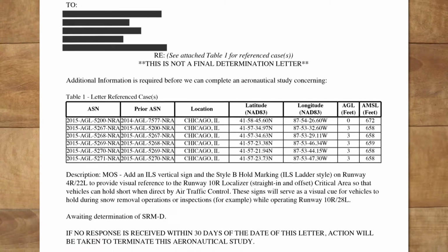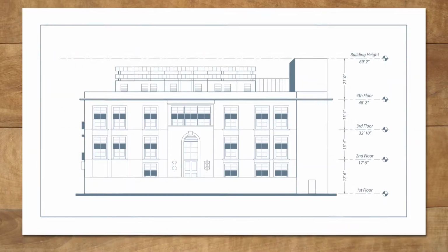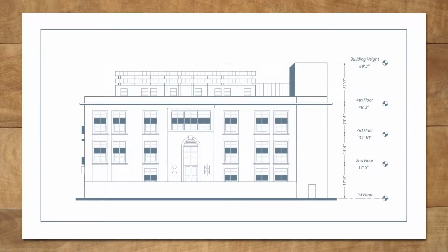As required, TechOps for flight procedures may request additional data on a specific structure or particular type, such as a building, crane, or fence. When recording the POIs for a building, some specific items to consider are: type of roof construction with vertical profile detail showing pitch and orientation with respect to the building footprint. Material composition of roof and exterior facade of building. Any additional exterior metallic rooftop or lateral building appurtenances, such as air handlers, ductwork, railing systems, and antenna systems. Building height, including the elevator shaft or any other structures, such as antennas.